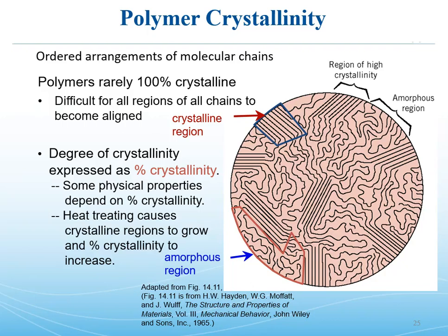Generally, heating an amorphous polymer, especially if it's heated very slowly, will cause the crystalline regions to grow, and the percent crystallinity to increase, and this is for the same exact reasons that metals and ceramics crystallize in the first place, and that's lowering total energy. The more closely associated those folded chain molecules are, the lower the energy. Even if it's polyethylene and you're only getting at best van der Waals bonds, chain to chain, sideways, it's still a bond, and a bond is a reduced energy state.